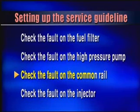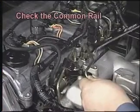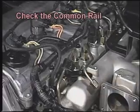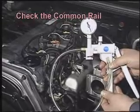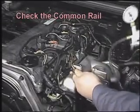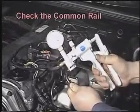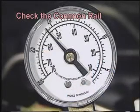Check the fault on the common rail. Next, you should check the air tightness in the common rail. In the circumstance shown on the screen, we suggest using a vacuum pump. For a vacuum pump, the number 1 high-pressure supplying pipe can be used for the adapter. Now, let's check the results after pumping. In this example of a normal vacuum value, the vacuum state of the common rail is excellent.